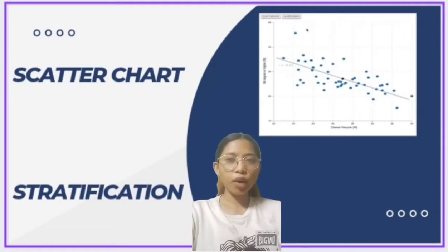Stratification. Now patterns can be seen. The data from reactor 2 and reactor 3 are circled. Even without doing any calculation, it is clear that for those two reactors, purity decreases as iron increases. However, the data from reactor 1, the solid dots that are not circled, do not show that relationship. Something is different about reactor 1.